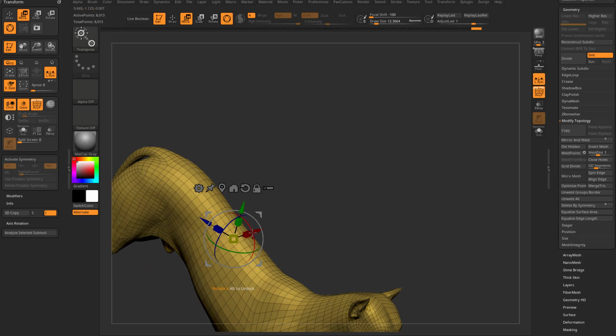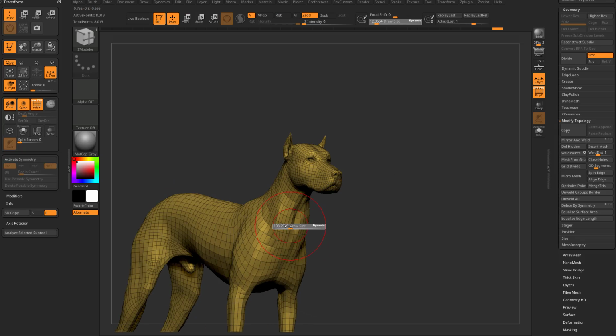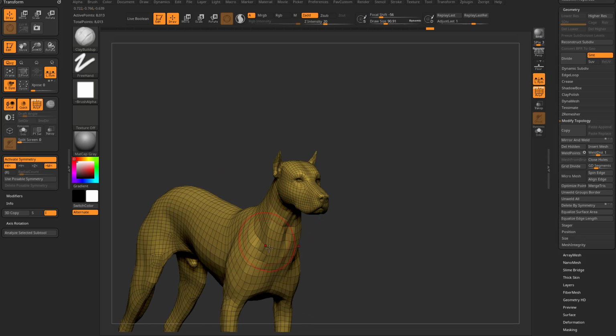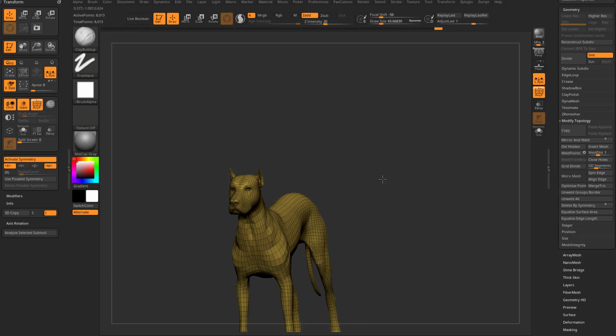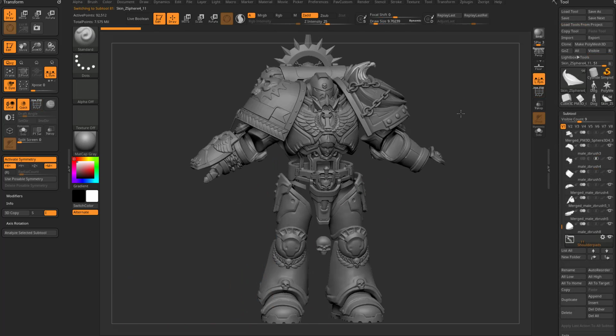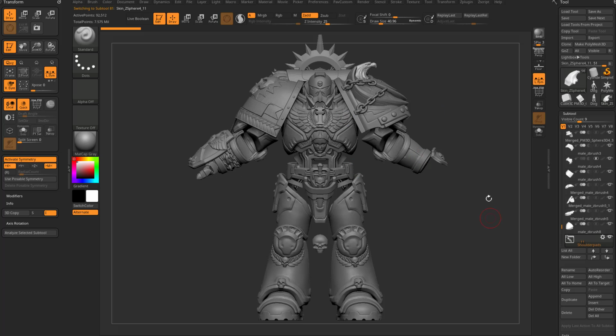If you want to fix it, you can hold down Alt and then point this to the front, and then hold down Alt and Shift, and we'll do 180 degrees for that. And now again, turn X symmetry back on. We are now symmetrical on this object here. So now I've got all sorts of symmetrical objects just kind of placed on this guy. So this is going to come in real handy as that arbitrary Gizmo work plane.